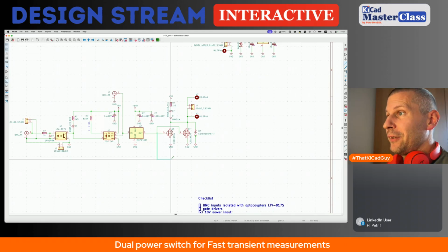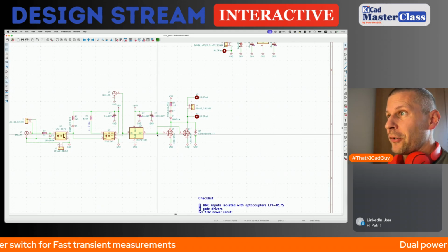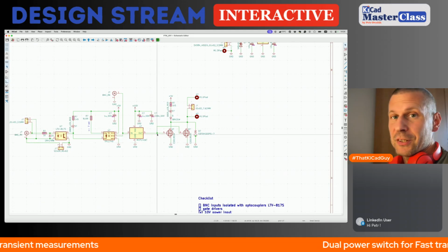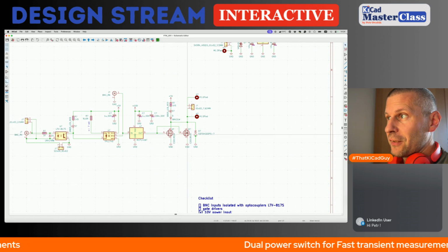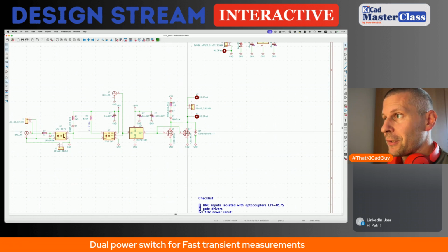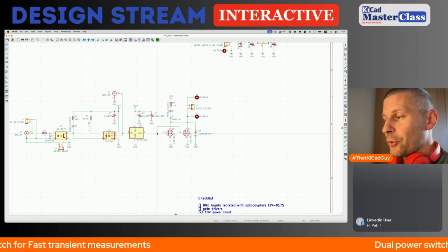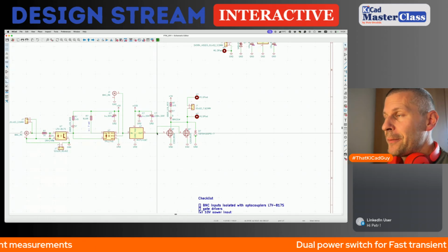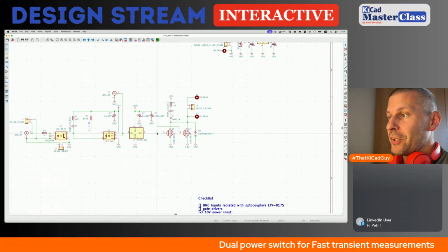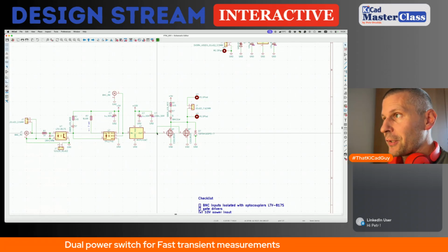But if we want to monitor the output, this wouldn't be very useful because we would use another switch. And if one of these MOSFETs is broken or short circuit, and we would use the auxiliary N-channel MOSFET for switching the LED, the LED would be off, but the switch would be constantly on if short circuited.